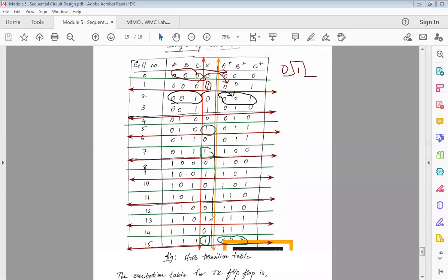So this is where we make those changes. Here I am telling my circuit that after 111, you go to 0. Instead of doing that, if I tell my circuit to go to 1, 0, 0, 0, then the count will continue. Understood?